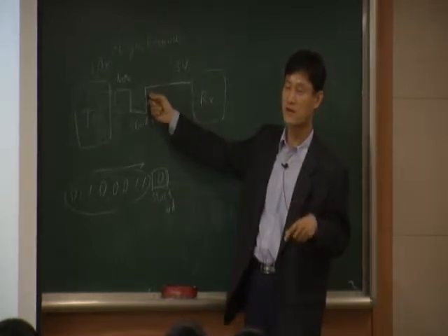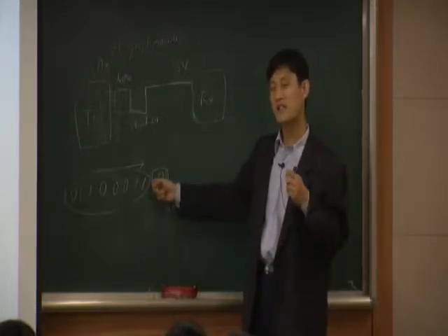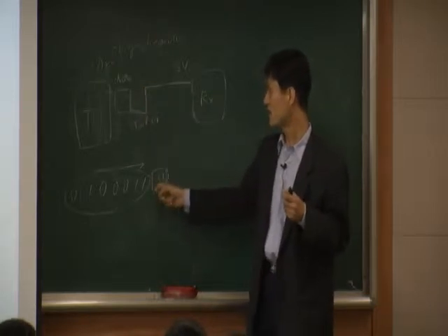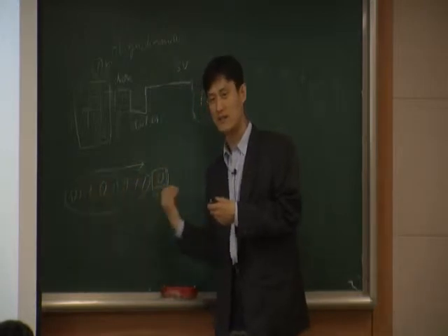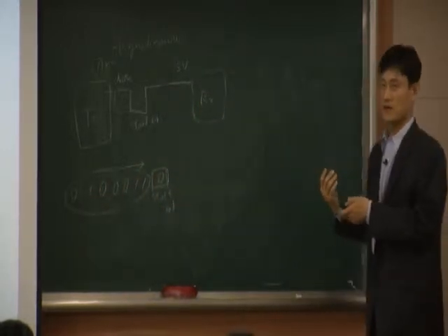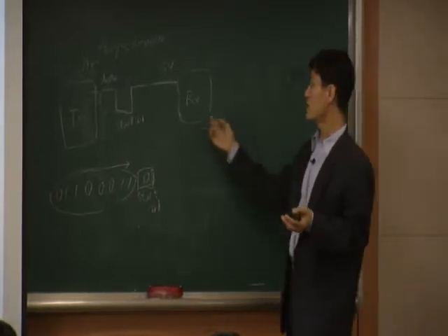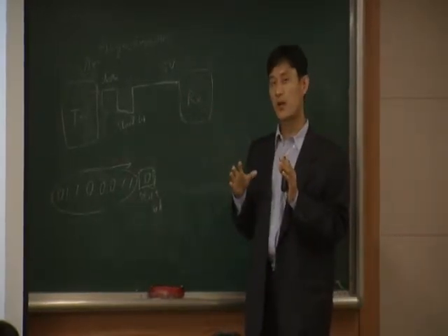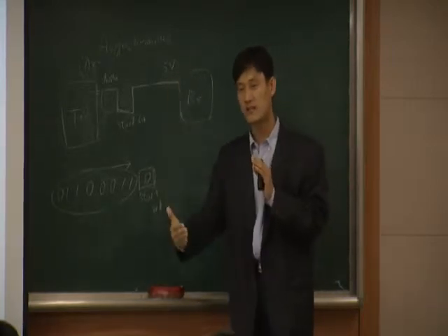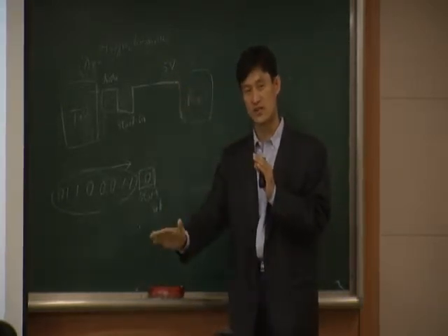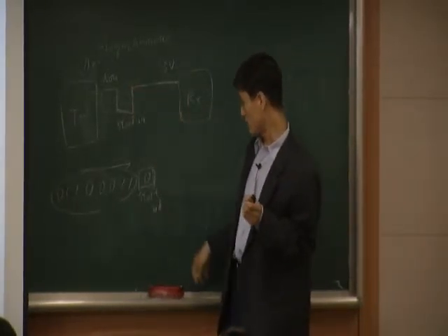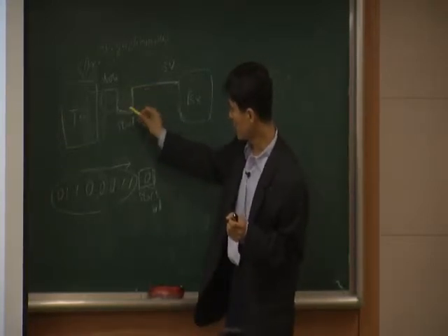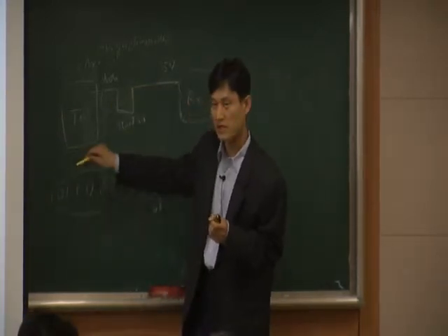That's the reason why we have a start bit. This edge basically indicates that my data is following. I'm bringing my data, 8-bit data. That's what you do. So it's very simple, right? The receiver is just watching and waits until it detects the edge, the high to low edge. That's all you need in the receiver. As soon as you can detect the edge, like this edge, then you can decode all the 8 bits.